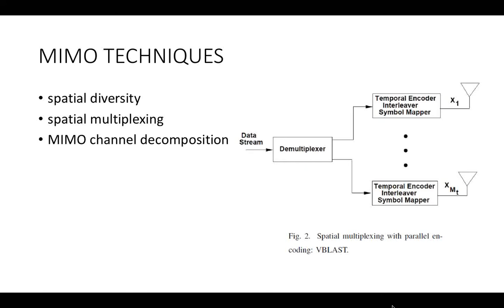We will skip the details of how it is realized and jump to the MIMO channel decomposition directly. The optimal way of communicating over MIMO channels involves a channel-dependent precoder, which fulfills the role of both transmit beamforming and power allocation across the transmitted streams, and a matching receive beamforming structure. Channel knowledge is therefore required at the transmit side for this method to be applicable.